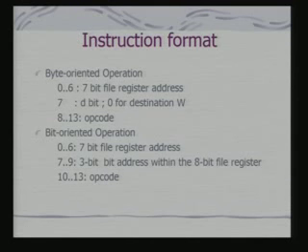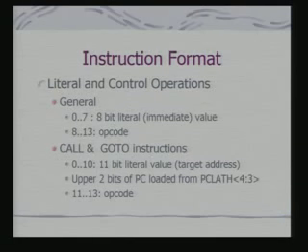For the bit-oriented operation, the interesting feature is that using 3 bits, you can specify exactly the bit number which is to be checked or modified in the file that you have specified in the address. Here also, bits 10 to 13 are used for the opcode.